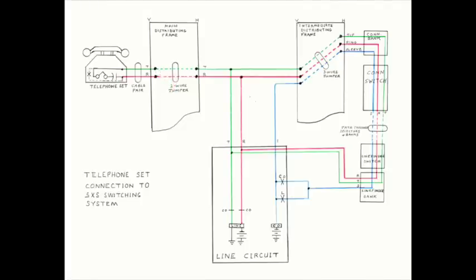In the central office, the CO technician will also have a service order that indicates the particular line circuit, identified by the line finder group and terminal number, that the cable pair should be connected to. The tech installs a 2-wire jumper connecting the cable pair to the line circuit. This physically connects the telephone set tip and ring wires to a line circuit and to the line finder bank and terminal.